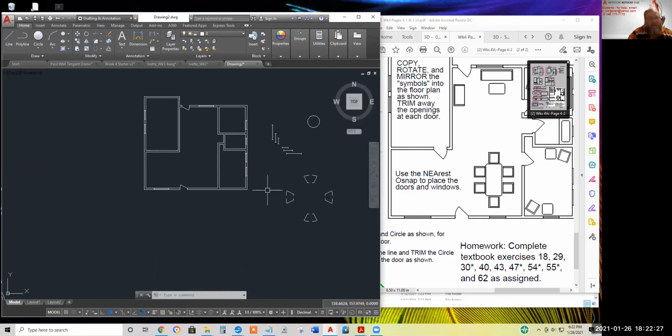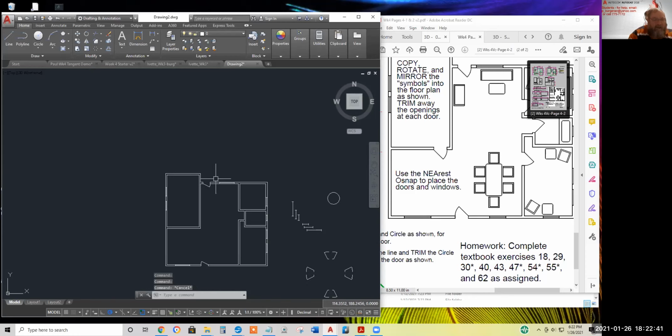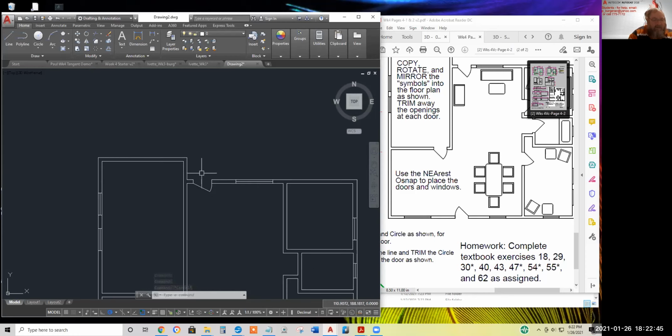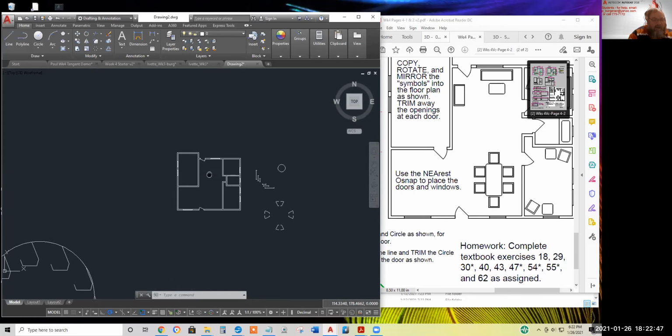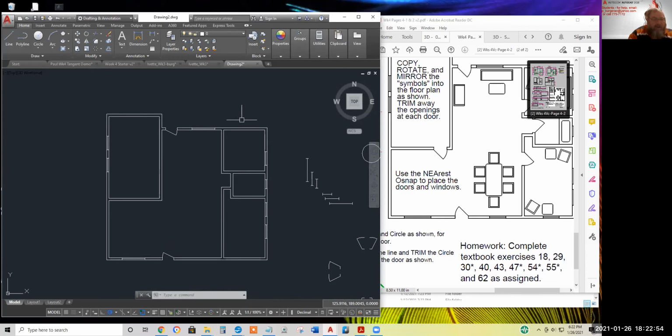By the way, I believe next week we'll learn polylines. We'll convert these lines into polylines. So instead of being separate lines, it'll be a continuous line all the way around the outside with the exception of the doors. And we can adjust the width of these with the polyline width option, different than line weight that we'll also get into next week.